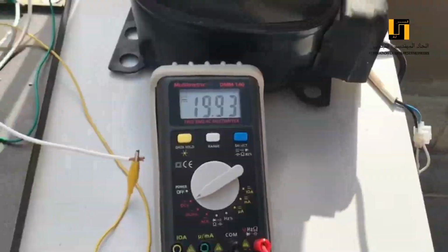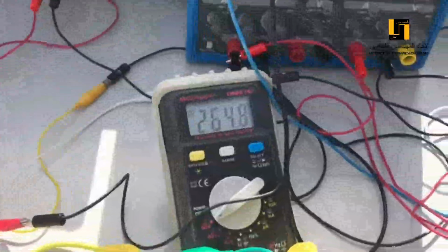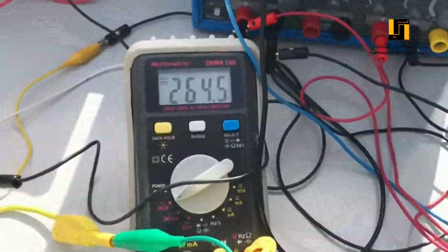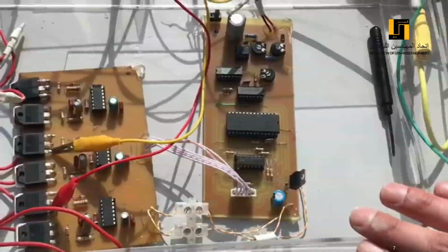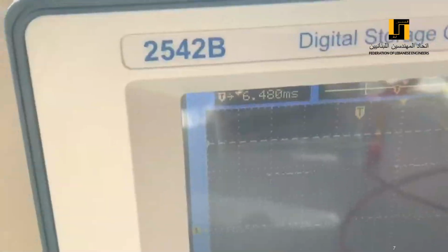The input voltage, as we can see, is around 20 volts from the solar panel. The output after the Luo super boost converter is 264 volts, which will in turn feed the 3-phase PWM inverter with V over F control. Now, as we can see, we can control the frequency and voltage thanks to the PWM and V over F control.